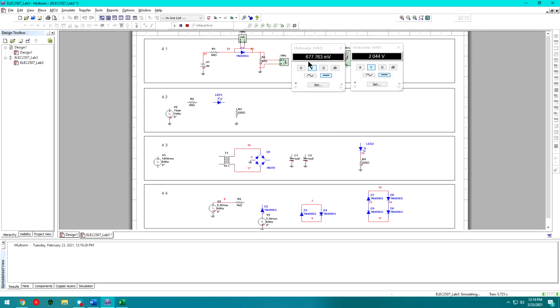Again, same sort of thing. We can see that the maximum forward voltage for this diode never actually happens. And we actually are only dropping around 2.7 volts of the 4 volts that we're inputting into the circuit. So we're losing around 1.3 volts to our source here.